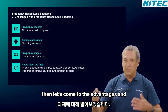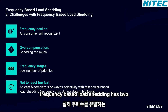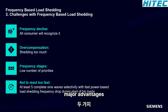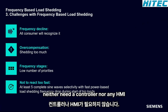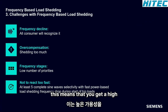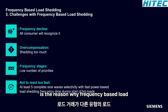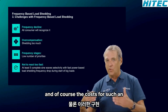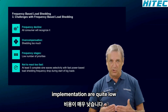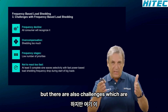Then let's come to the advantages and challenges. Frequency-based load shedding has two major advantages. For the actual frequency triggering, you need neither a controller nor any HMI. This means that you get a high availability. This also is the reason why frequency-based load shedding often is used as backup to other types of load shedding. And of course, the costs for such an implementation are quite low. But there are also challenges, which are shown here on this slide.